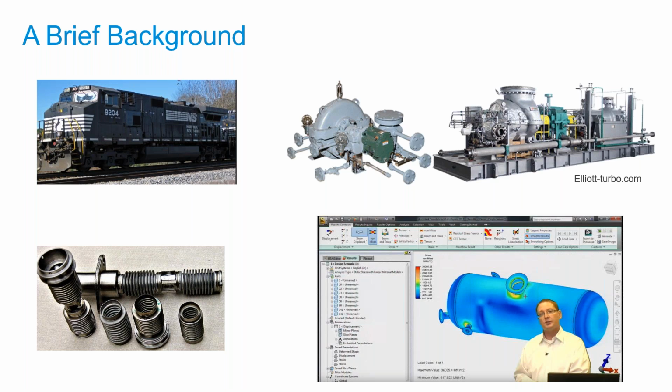And it was at that point that they asked us to do some simulation, some validation. And there's a couple of reasons there, right? So obviously with the bellows there, it needs to be able to deform a certain amount. We also need to avoid certain frequencies that the vehicle might experience. So we were doing some natural frequency analysis. But initially, we weren't doing any simulation. It was on the shelf, 3.5-inch floppy disks. We had it available to us, but we weren't doing it.